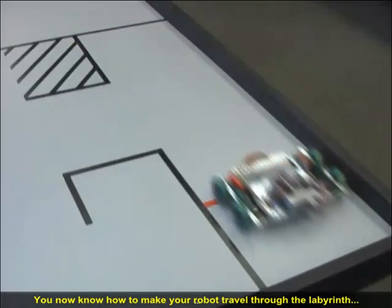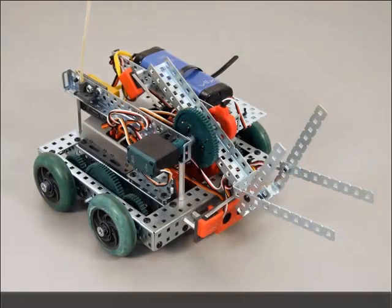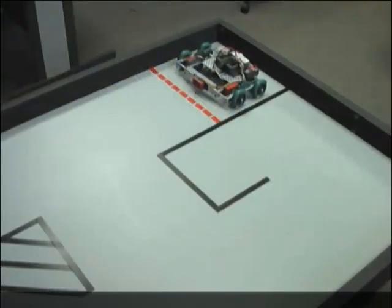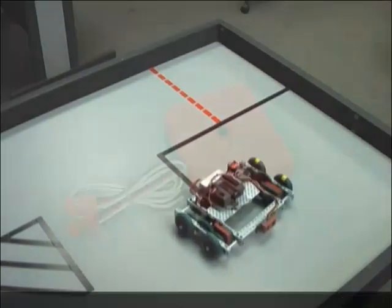You now know how to make your robot travel through the labyrinth by controlling how long and how fast the motors spin. It's a great start, but not a great overall solution. The manual adjustments you made won't be the same for every robot. And as the battery power drains, the robot will travel shorter and shorter distances in the same amount of time.